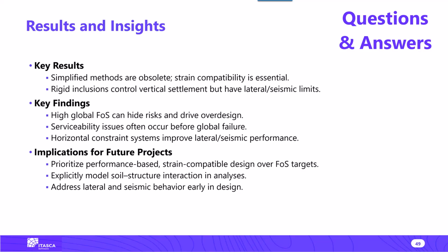Cool. And let's see, next question. Do you recommend importing liners or creating them from zone faces? Well, it could go both ways. In this case, I generate the liner directly from the faces. So typically, in my experience, if it's possible, it's worth spending a little bit more time organizing a mesh so that you can use the faces to generate the liner. It tends to work better.